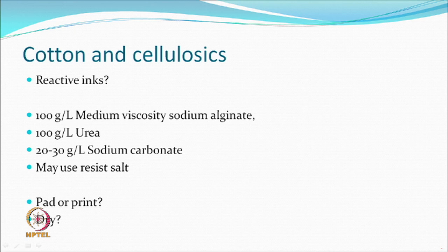If it's a thick fabric and you don't want so much chemical to be used, you can just put it on the surface. That's no problem, but padding is cheaper. And of course, you dry. I mean, you're not going to be taking a wet material inside the digital printing system. So, all this is important. Whatever cost it has and whatever complexity, you have to do it.